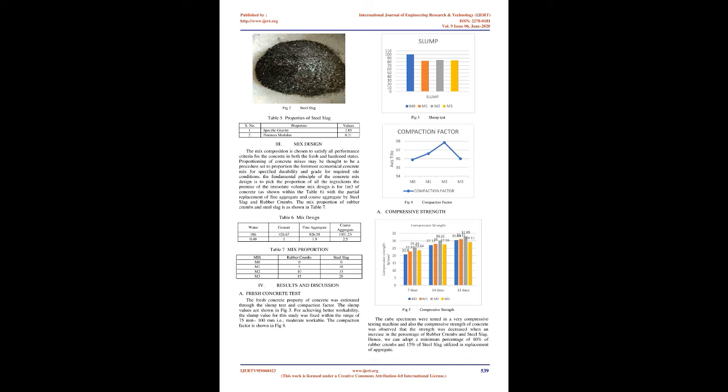Cement might be concentrated to 10. You choose the use of OPC grade 53. B. Fine aggregate. The natural river sand is the most ordinarily used fine aggregate in concrete. The properties of sand will affect the strength of concrete in a great manner. The fine aggregate shouldn't have high clay and silt content since clay will affect the behavior of cement and reduces the strength of concrete. The fine aggregate should even be free from any organic content.